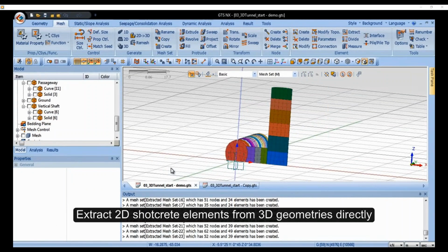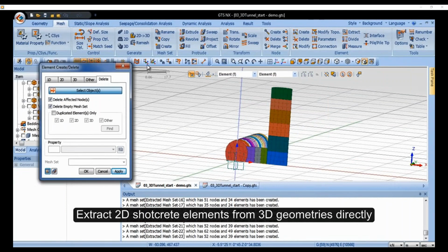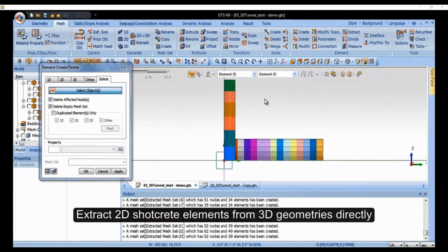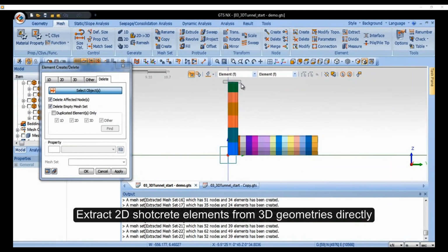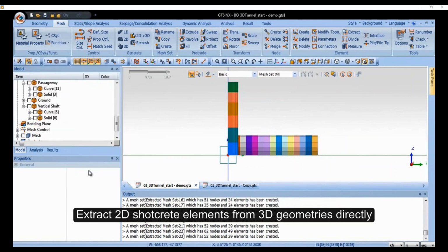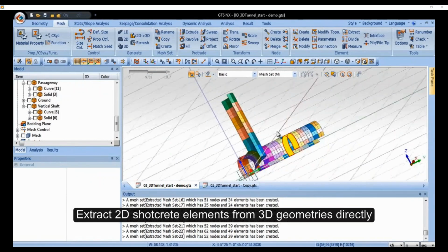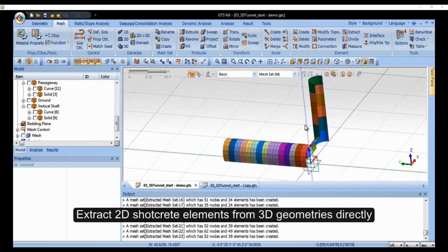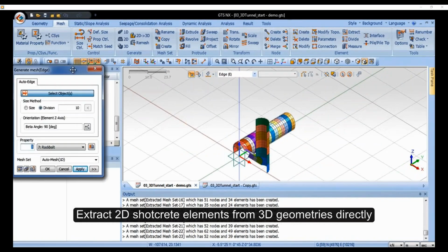So now if I hide the geometries, this looks like I have created solids, but they're actually shells. They're hollow inside. So I need to get rid of the extra faces, the exit, and of course the faces corresponding to the models that don't match. So there's no lining, there's no floor slab, and we're also deleting at the end of the tunnel, so that when I spin it, you see that only the supporting lining system is retained.